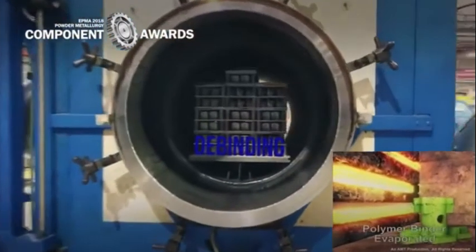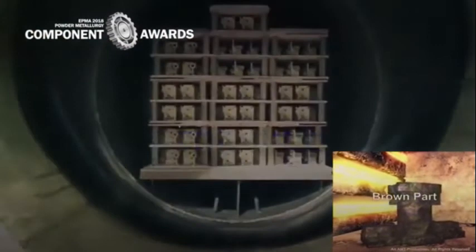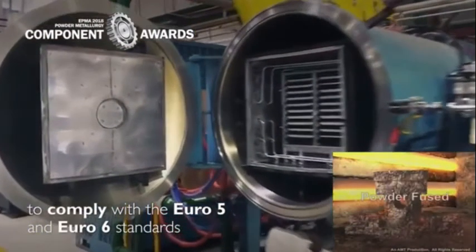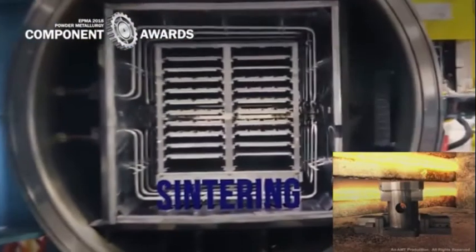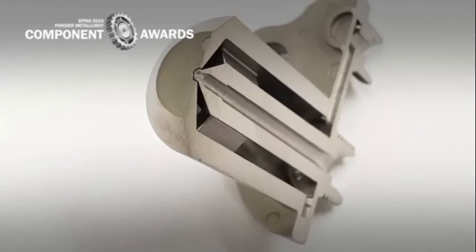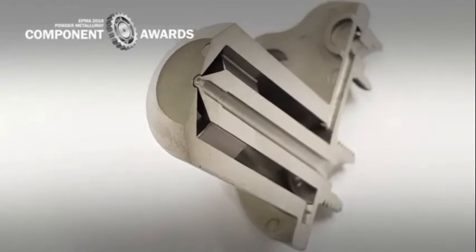The OnePiece nozzle is applied in a selective catalytic reduction (SCR) system for commercial vehicles in Europe to comply with the Euro 5 and Euro 6 standards. Urea is connected to the central hole and compressed air is connected to the other channel. The compressed air is pumped into the nozzle, exiting through the ring at the nozzle tip.